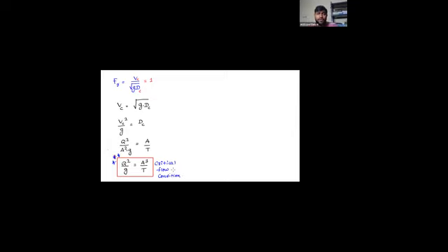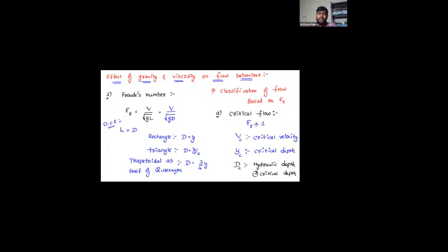When do you say critical flow? When you send a discharge Q such that Q squared by g equals A cubed by T, then the critical flow condition is attained. Then the Froude number is equal to 1. I hope you understood the meaning of critical flow. Sir, why are you saying critical, critical, critical? What is the real meaning behind it?